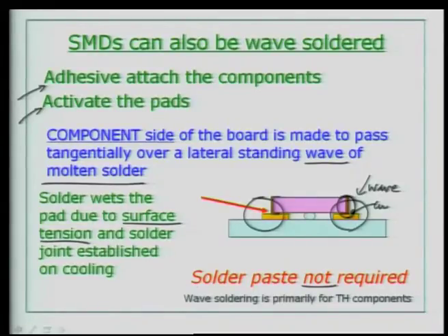But as we have moved on over the years, today the percentage of wave soldering for surface mount devices has considerably reduced, and today we are talking about wave soldering for through hole components and reflow soldering for most of the surface mount devices, including BGA.